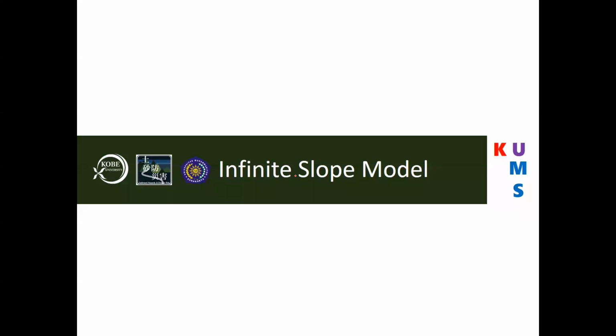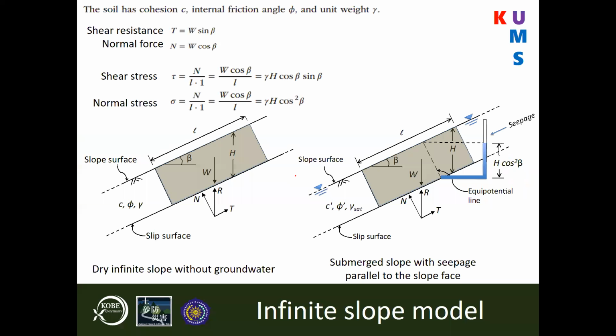And to start, we'll start with the infinite slope model. So that's, I think, the simplest model. That's why we started with it. And we consider soil with a cohesion c, an internal friction angle of phi, and rho will be the unit weight. So we need to define two things.